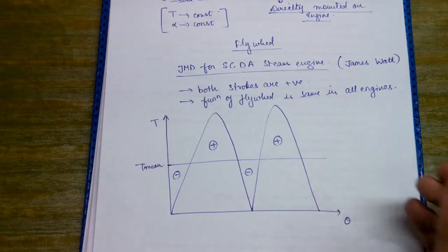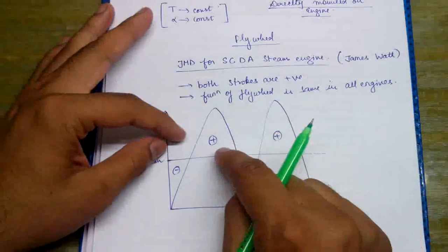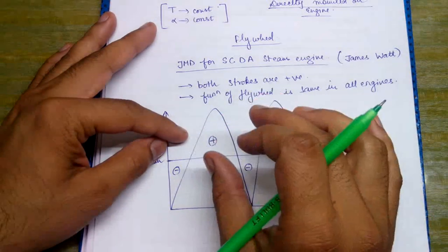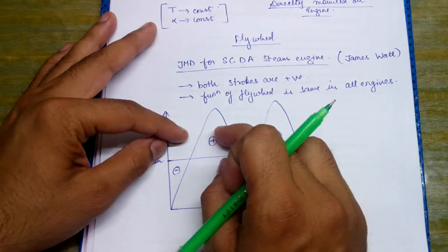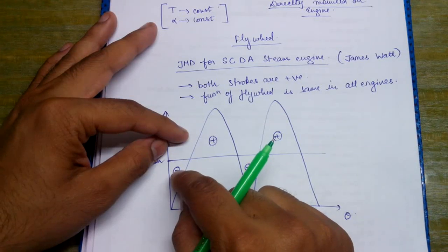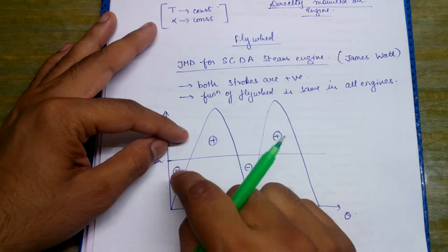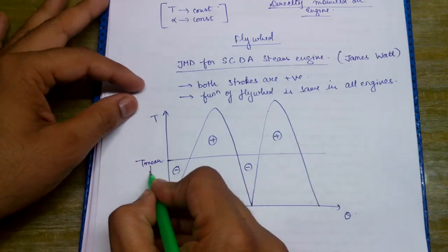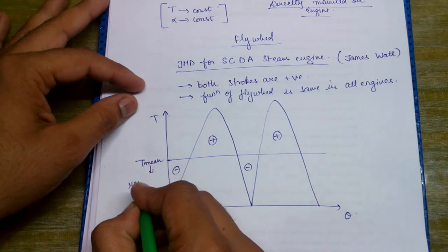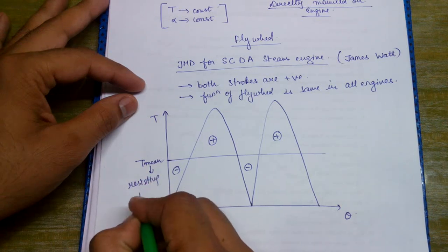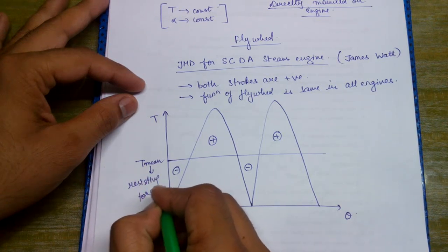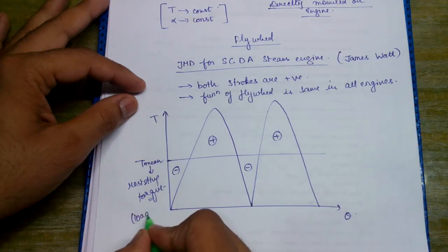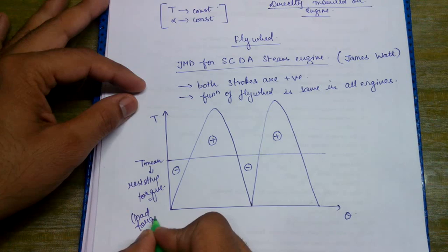Now what do we understand by positive and negative? Positive simply means that the energy in this region would be more than required, and hence it will be stored in the flywheel. And negative means the energy will be deficient, and hence the stored energy in the flywheel will be released. This mean torque is also called the resisting torque, or the load torque.